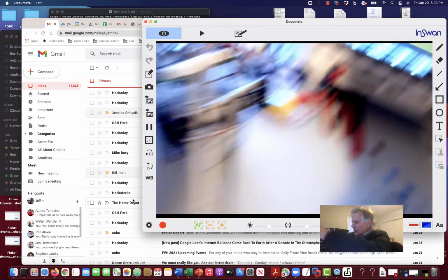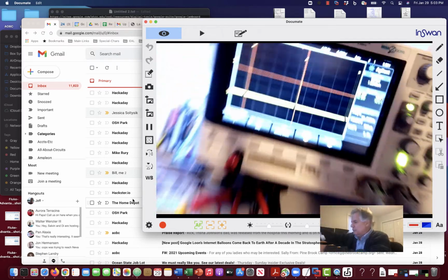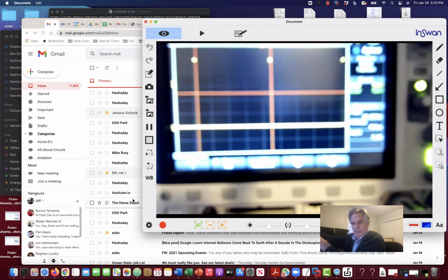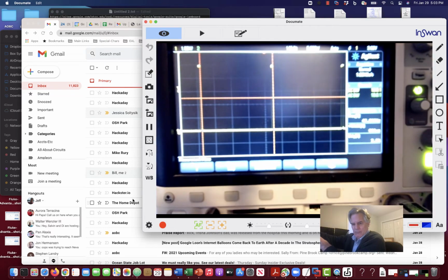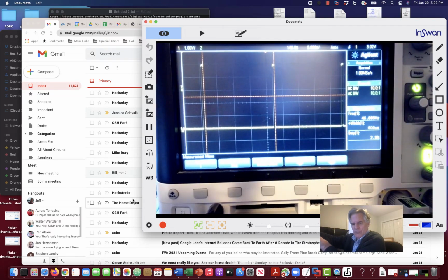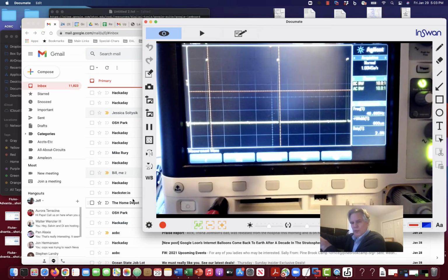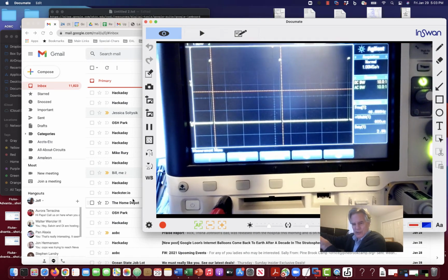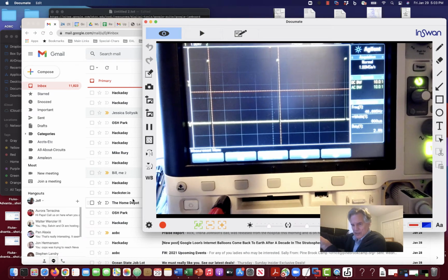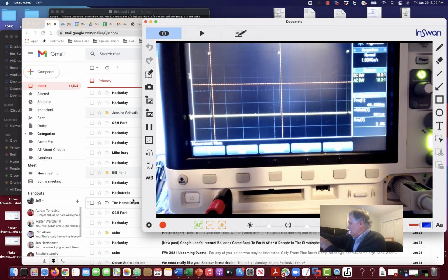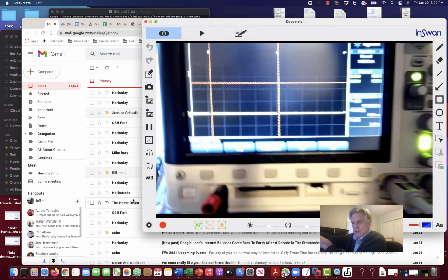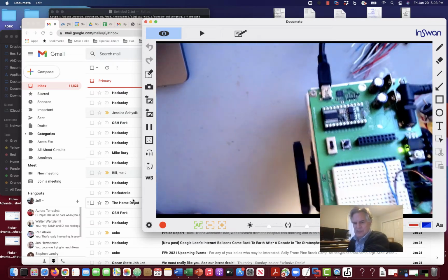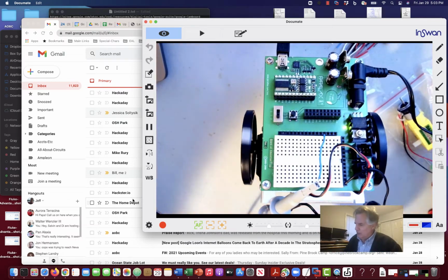Now our pulses are, as you can see here, very narrow. We're down in the 2% area, 2.8%, closer to 3. Frequency is around 46, almost 47 hertz. Like I said, it really should be nearly constant. But the width is now 0.6 milliseconds or 600 microseconds. So obviously there's a feedback mechanism inside this, the little boxes that these motors are based on.